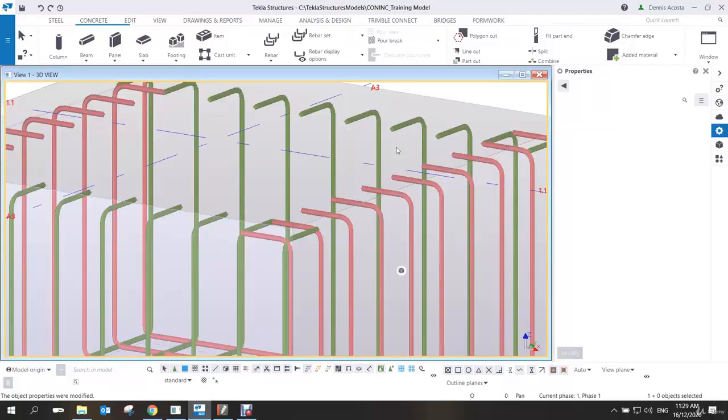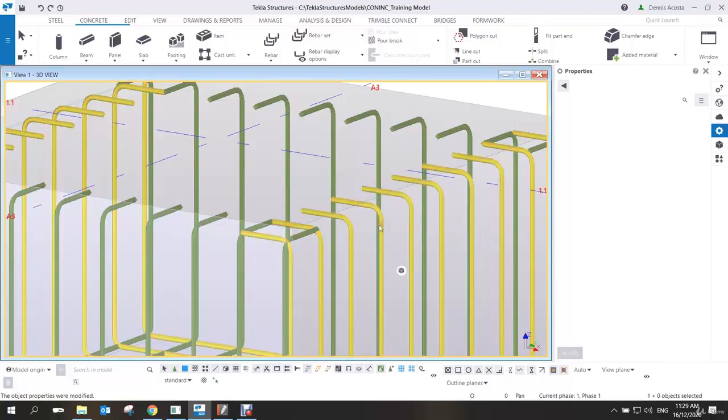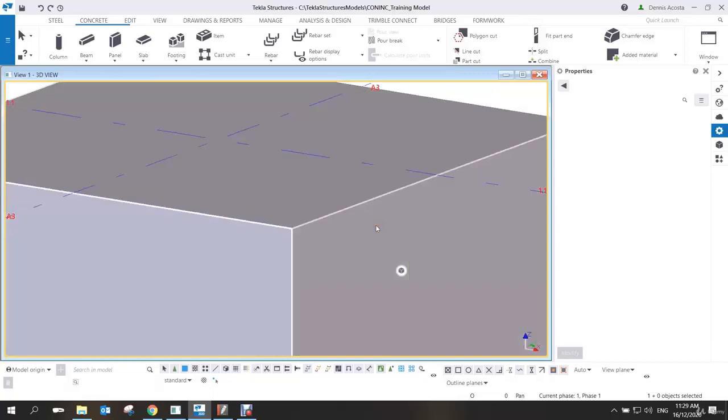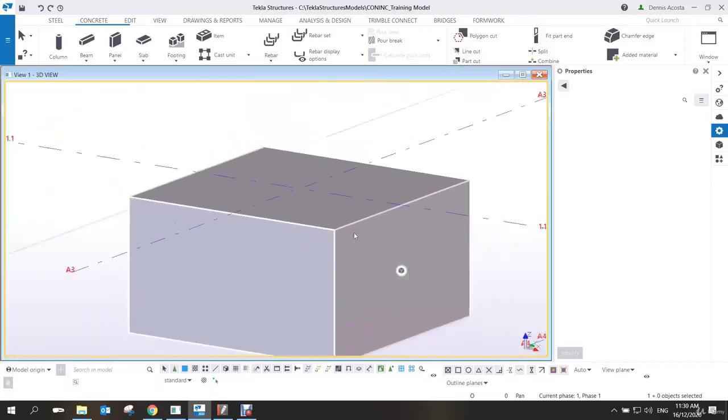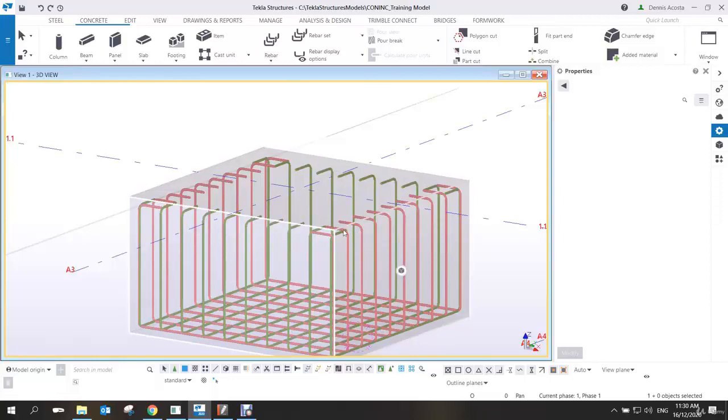But again, if you have difficulties on that one, you can always press control 2, control 4 anytime. So first, pick the part to reinforce, control 4. Once you pick that one, then control 2 and then pick the edge. So at least you can pick the object itself.